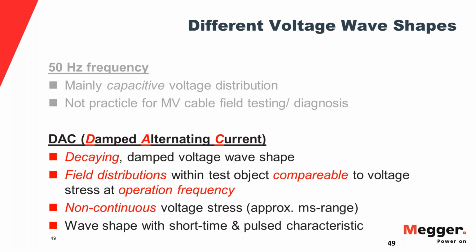And that voltage, there are seminal papers on that, was the first to be established to get the same results as true 50 and 60 hertz testing. Inception voltages are comparable, activity is comparable, magnitudes are comparable. So that is the go-to technology for diagnostics PD testing.